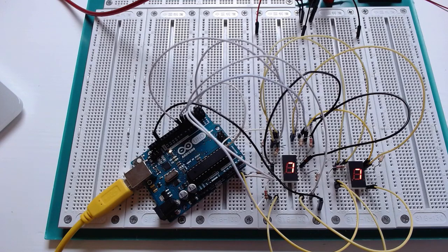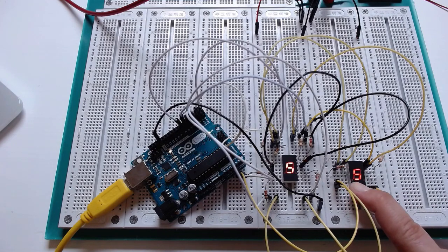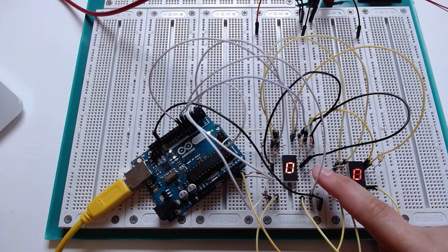Okay, in a common anode display, we give a 0 when we want the segment to be lit and a 1 when we don't want it to be lit. It's kind of opposite logic, but we do use that when we're using the BCD to 7 segment decoder, because the outputs of our 7 segment decoder are active low. The same thing holds. This would still be the wrong way to wire up a common anode display. We need to have 7 resistors, 1 resistor for every single segment that we're going to drive.